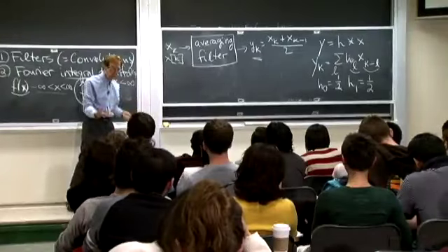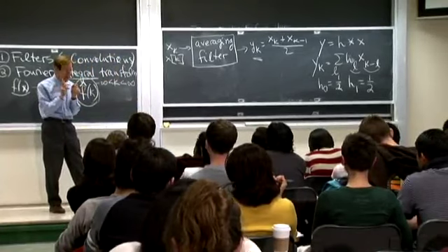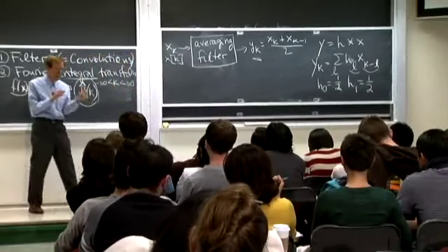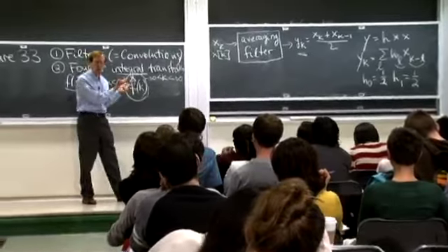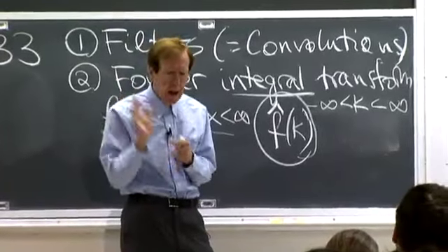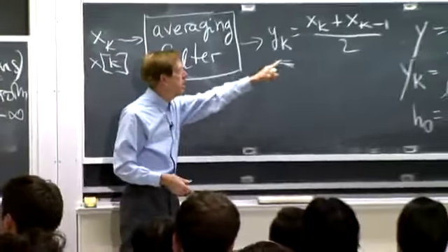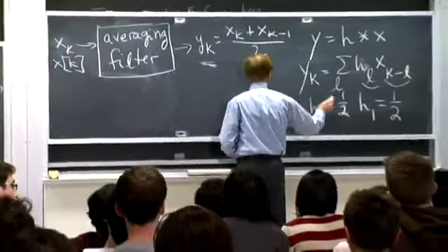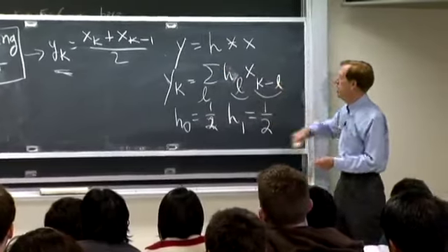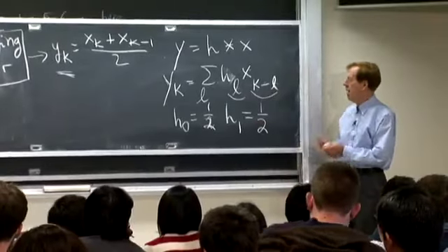But you want to keep the signal. So it's always this signal to noise ratio. That's the SNR, PSNR. It's a constant expression, signal to noise ratio. And we're expecting here that the signal to noise ratio is pretty good, high, mostly signal, but there's some noise. This is a very simple, extremely short filter. So this vector h is a proper convolution. You could say h has infinitely many components, but they're all 0 except for those two. Do you see it?